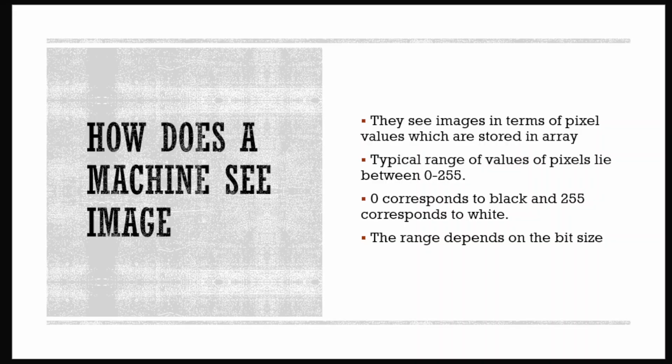When you're taking a picture with a camera and you overexpose it, the exposure time is large, so more light is allowed to enter the sensor. It gives the sensor values more time to saturate. That's why you get bright images when you overexpose.